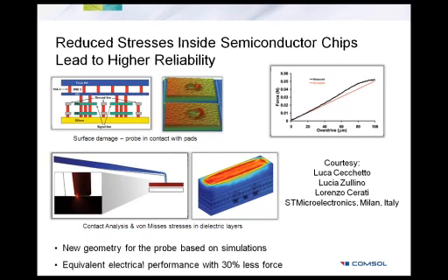In the semiconductor industry, what happens is probes are used to usually connect to electrode pads or vias, call it, in the circuit for electrical testing purposes before they actually package the device into an IC chip. Usually there are multiple layers of metals below these electrode pads or vias, which are separated by dielectric layers. These are called interlayer dielectrics.